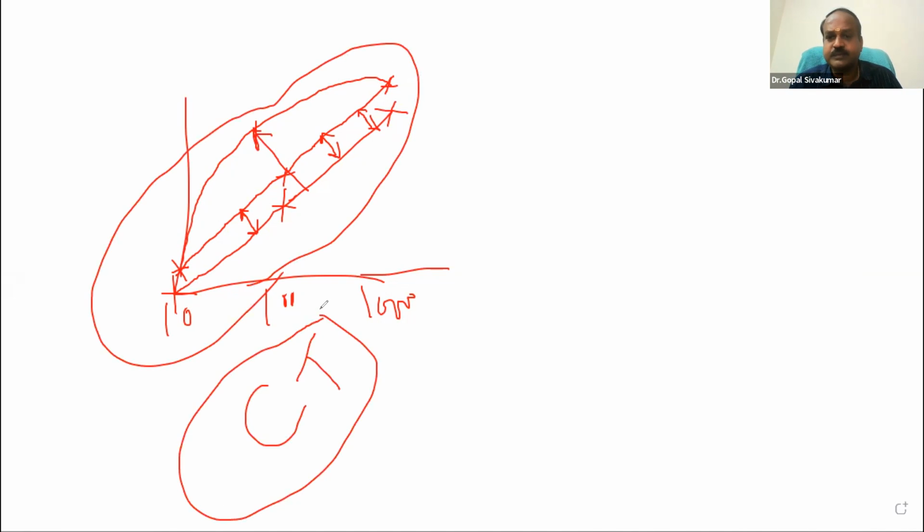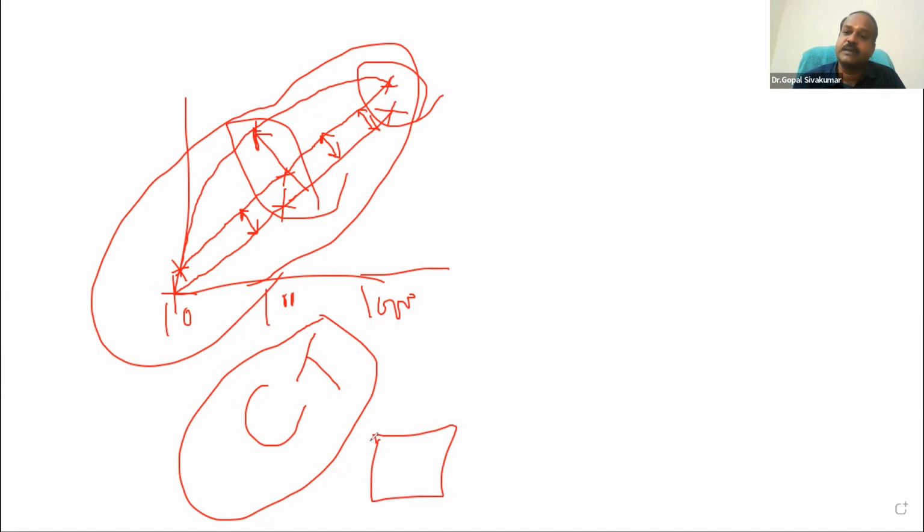Am I correct? In which range is bias more? In which range is bias less? You create a table. Morning, your watch will run 10 minutes faster. Afternoon, your watch will be 15 minutes faster. Evening, your watch will be 20 minutes faster. I am asking you the time in the evening. What will you say? You will minus 20 minutes. Now, how is your watch behaving? Is your watch behaving in a linear manner? No. Non-linear. So, understanding linearity is important if you want to create a calibration table.